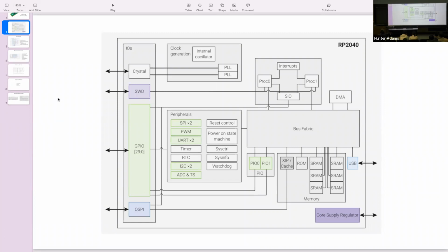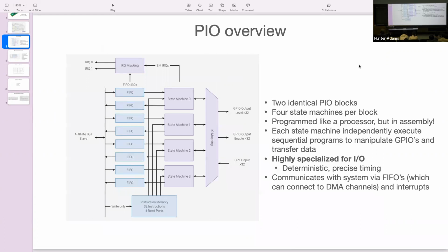So there are a few levels of abstraction here. What I would like to do now is consider one of these PIO coprocessors and the stuff that's contained within it. Each PIO block, as it's called, and there are two PIO blocks, can contain up to 4 state machines. You can think about a state machine as being a program that lives on this particular PIO block. Those programs may be entirely independent from one another, or there do exist mechanisms for signaling between state machines on a single PIO block, and we'll talk through some of those signaling mechanisms.